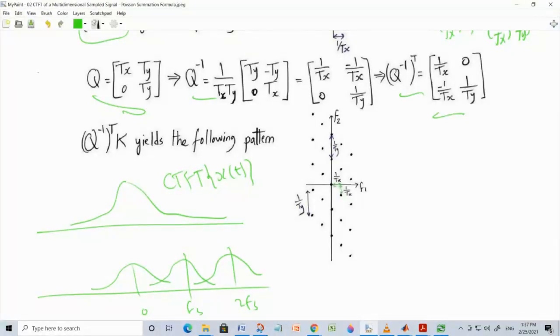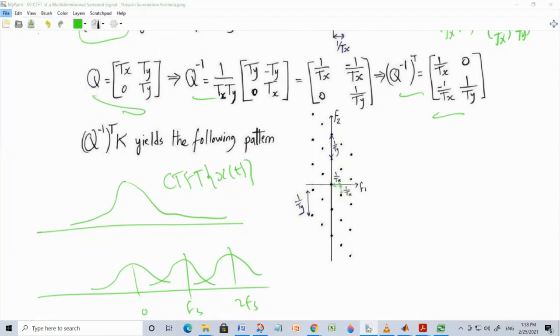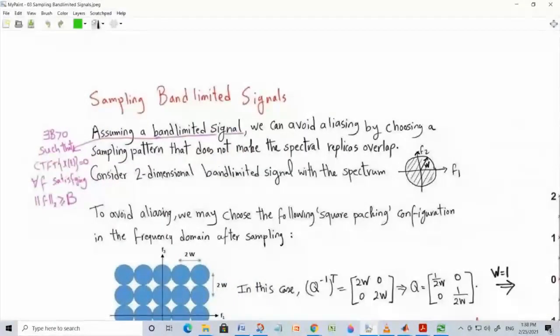By removing part of the signal, you are saying that in your application those frequency components are not really important, and so we can just get rid of them. So typically we force signals to be band limited. Band limited is mathematically a very strict concept. A band limited signal will have a definition like this.